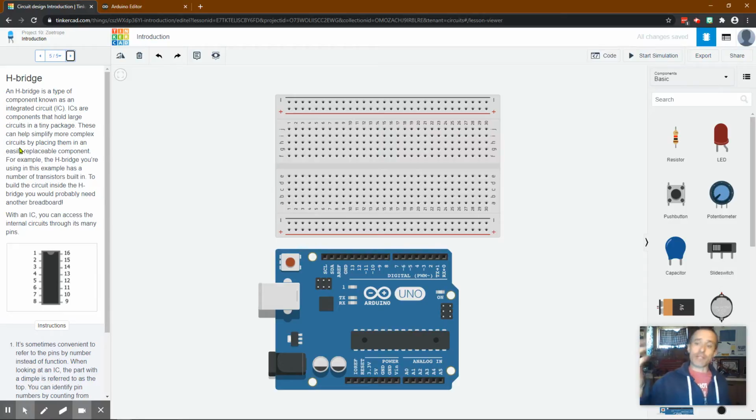And remember, the transistors were these electronic switches, right? Very much like relay switches, almost like a light switch, but in this case, we're sending digital power. We're sending like 5 volts to it, and that'll flip a switch, and that can control a higher amount of voltage.